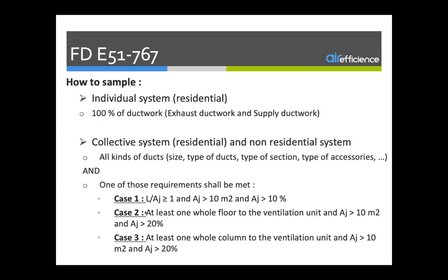Now, how to sample for individual system. 100% of the ductwork has to be tested, exhaust ductwork and supply ductwork. Now for collective system and non-residential system, in large air duct system, the test can be performed in a part of the system.